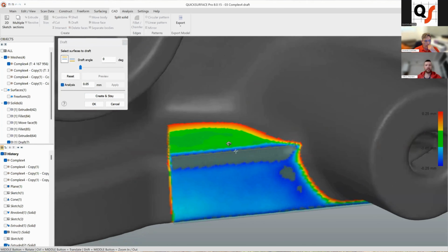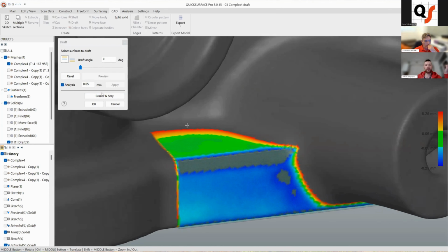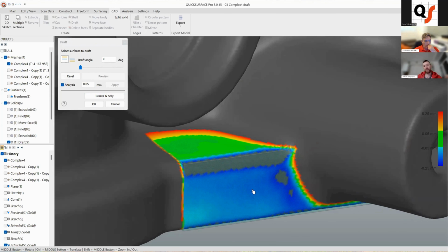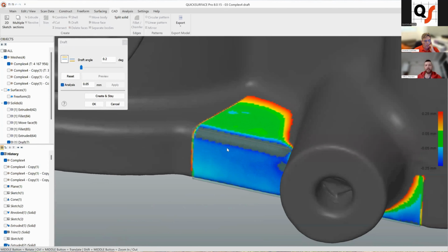Switch on analysis. Basically, at this point, it removes any draft from your extrusion. And as I have previously used draft on this side, it was bouncing outside. So draft on this side is quite good at the moment. But you can always turn it up or down, depending on how much you need. So this way you can get perfectly aligned surfaces to your scan data.